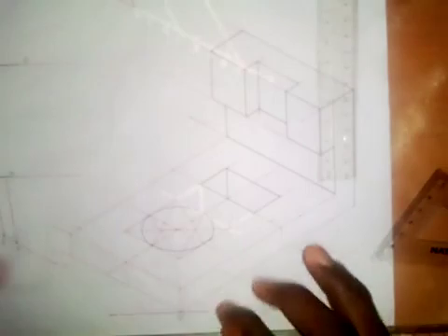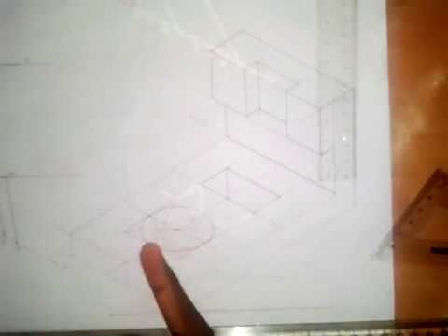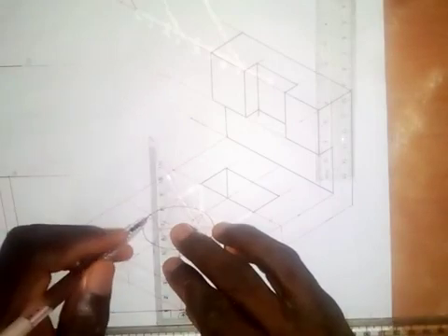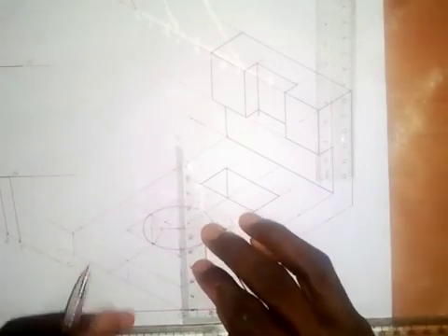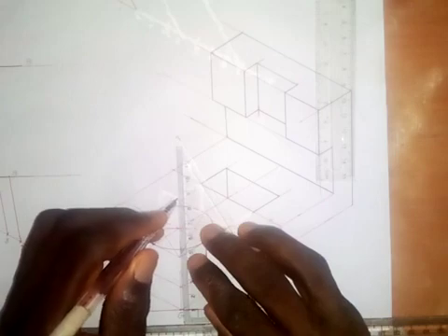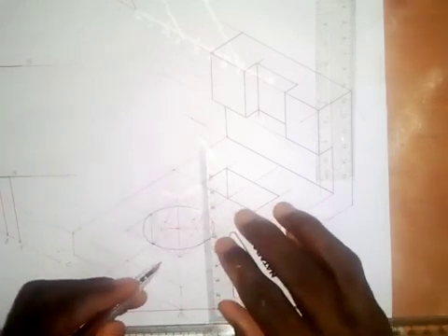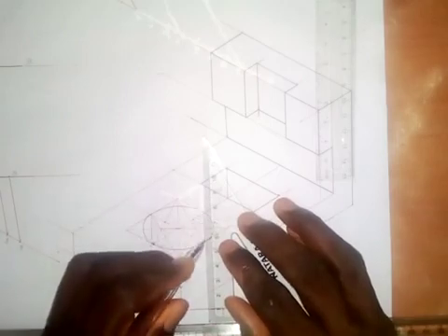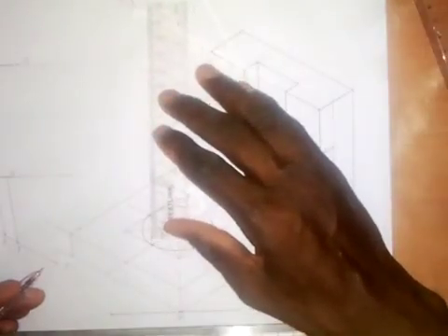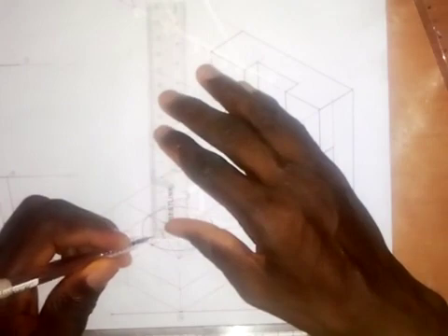So now, I've created the isometric circle here, but sometimes depending on the thickness of the object, as we have that this is 15 millimeters, we may need to work on the down part of this circle. Let me see if that is going to work. What you need to do in that case is, you come to this point here and you draw a vertical line down, and you come to this point also. So take down a vertical line here like this, and draw a vertical line from this point too. What we need to do now is, on this line, we are going to take a measurement of 15 millimeters. Okay, we get 15 millimeters here, so this is 15 millimeters.